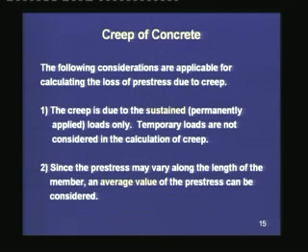But again, in some situations, the full live load may be considered temporary, like in a bridge structure. Hence, appropriate judgment has to be made to consider whether the live load is sustained or what fraction of the live load is sustained, and to calculate the creep based only on the sustained load. The temporary load need not be considered to calculate the creep.